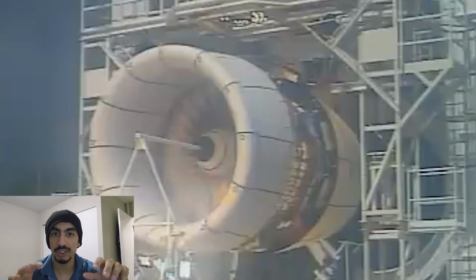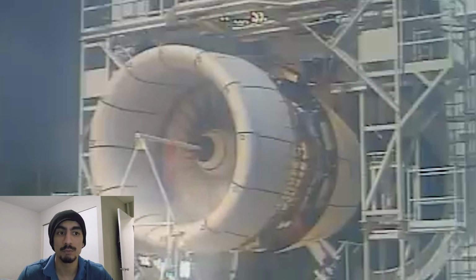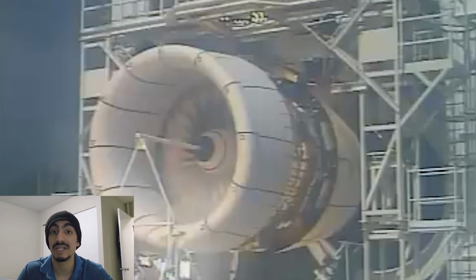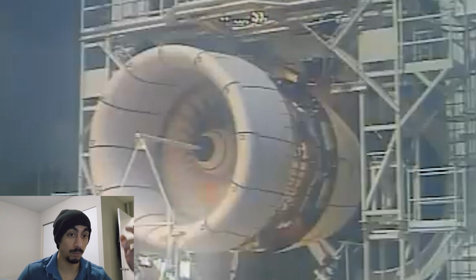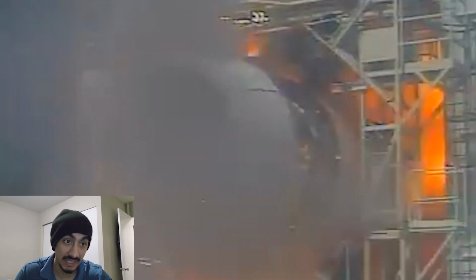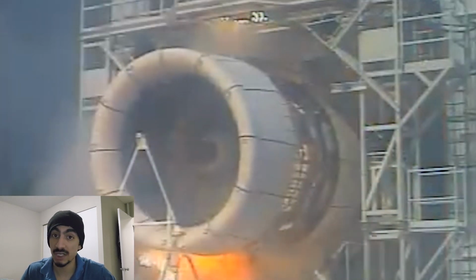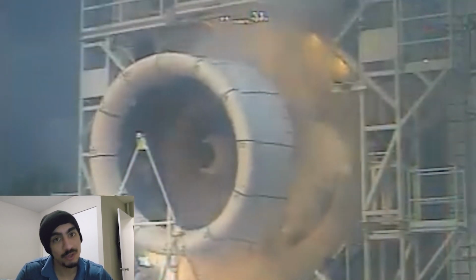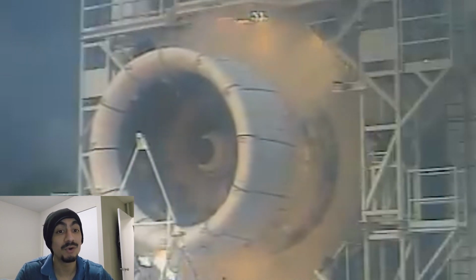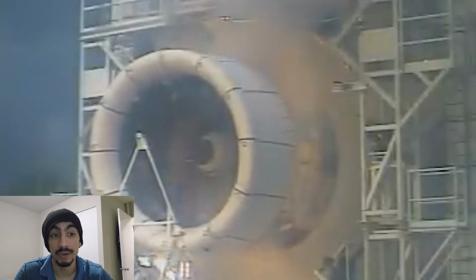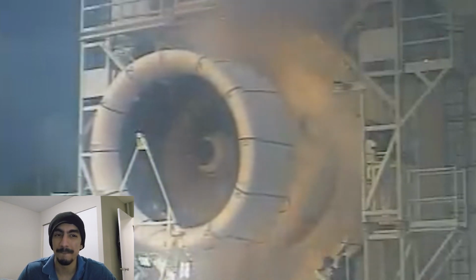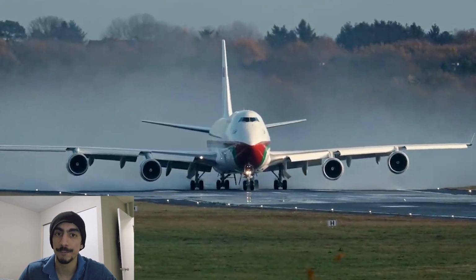Because when you're building commercial jet engines, okay, like the ones in the Boeing 737, the manufacturers have to prove that these engines can handle a certain level of bird ingestion. And it's exactly what it sounds like. They will fire bird carcasses, as you can see in the video. Generally, it's chicken or turkey types of birds into a running turbine on a test stand. And it's pretty grim, okay? But it's the only way to ensure that the engine won't just explode the moment a bird hits the fan blades. And the goal is to avoid what we call an uncontained engine failure.